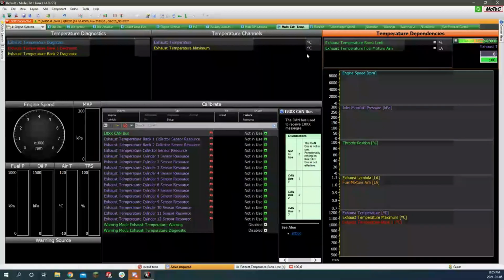If you see the temperature in one cylinder is different from other cylinders, but we can't really do that. All we can say is that if it's in a normal range, if it sits at 920 degrees Celsius all the time, we're probably fine. If it spikes up to 1100 every once in a while, that's an issue. That's pretty hot. So we just want it to be consistent, and we'll get that wired in at some point.